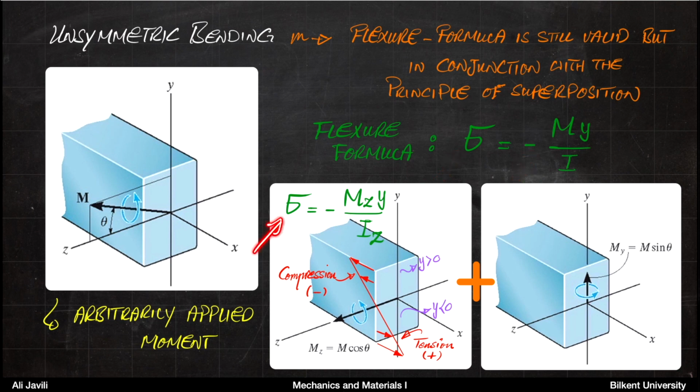So stress equals minus, and again the minus comes exactly from this observation that we had, minus moment with respect to the z-axis, divided by moment of inertia with respect to the z-axis, times the distance, but the distance is also the distance from the z-axis.